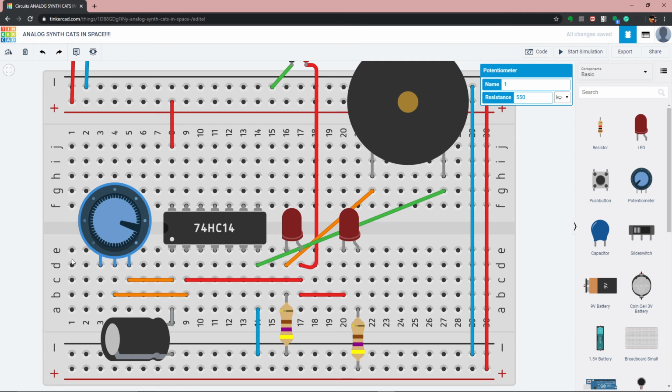So this second part, this part that can control, so if the wiper is all the way over here and then this is all the way over there, this resistor across this bit of the circuit is going to be pretty high. So that's good to know. And the second half of it is going across here, and that variance is what we're hearing in the pitch change right now. You can also, I'm going to do a thing really quick where I just play with.